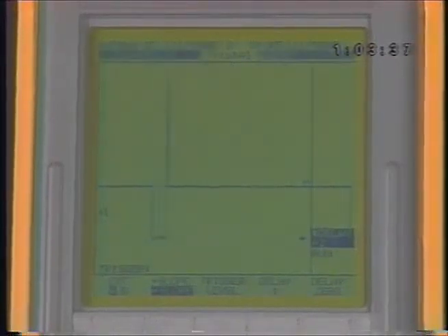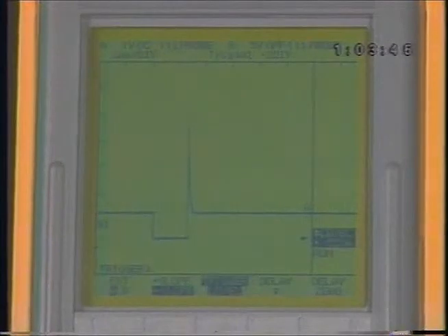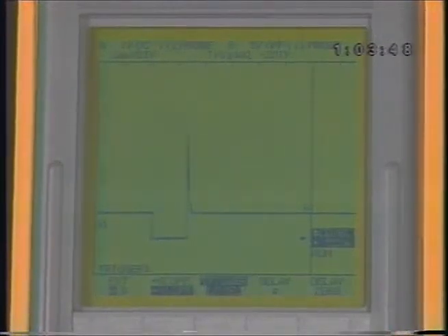Adjust the voltage scale and time base to display 1 or 2 waveform pulses. You may have to reset the trigger level after adjusting the voltage scale. Now you're ready to measure the waveform's on time.